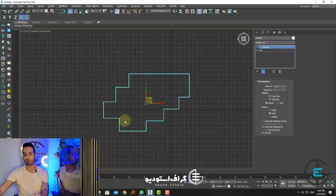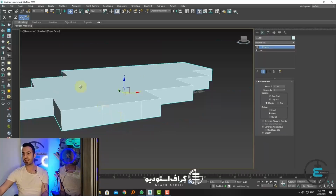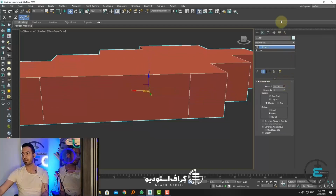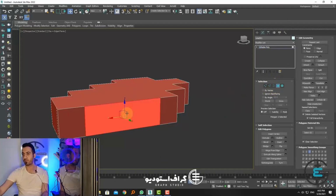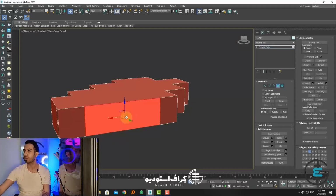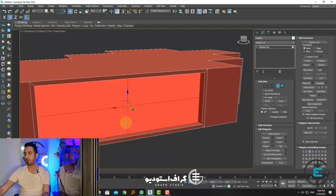Now the spline work of ours is finished. We want to take it to a geometry state, so we can easily convert to editable poly and work on it. Here, for example, let's assume that a door is in this shape. I take it further back. One time with tessellate, I give it a few more stages of subdivision. For this I activate these, and here, inset with polygon in this shape, you see I keep shift pressed and I was able to easily model now a window or anything that is here.